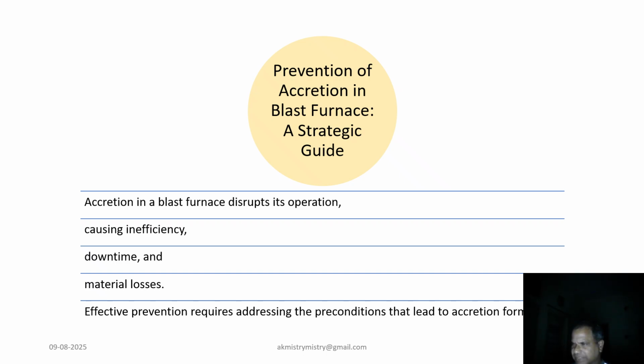Accretion in a blast furnace is a significant operational challenge. It disrupts its operation, causing inefficiency, downtime, and material losses. To effectively prevent accretion, it's crucial to address the underlying preconditions that led to its formation.